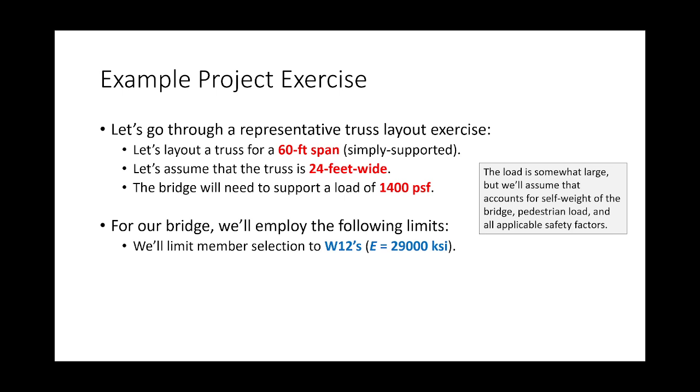And because it's steel, we know that E is 29,000 KSI. Now, as you all are writing down these parameters, your pencils are gonna wear out pretty quick because I'm gonna show you a lot of results really quick. So just be aware of that. We're going to limit the stress on each member to 36 KSI. And I'm going to go ahead and tell you that if there's any one piece of this problem that's kind of a bunch of junk when it comes to real life, it's probably this.